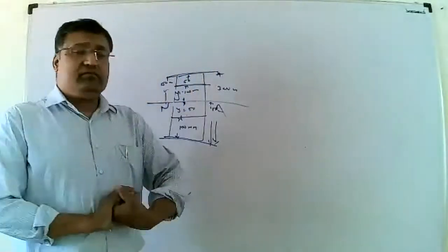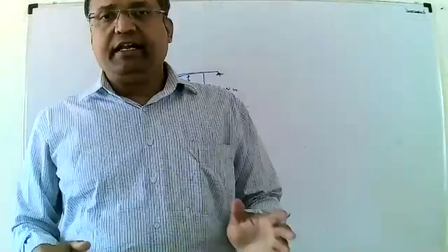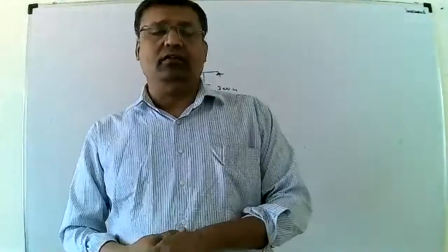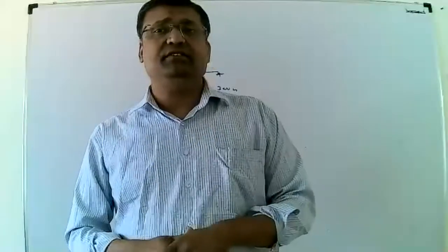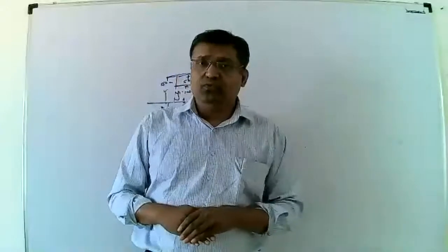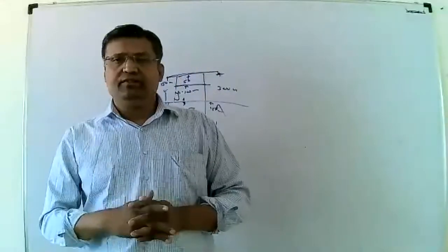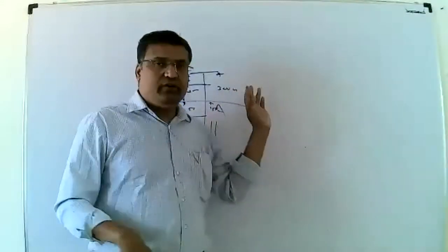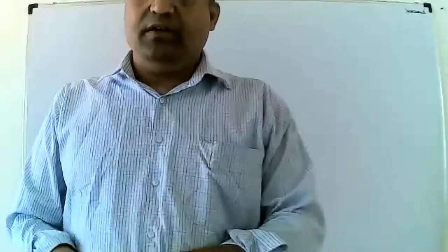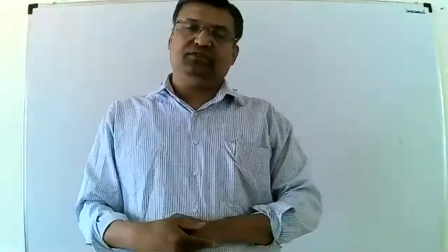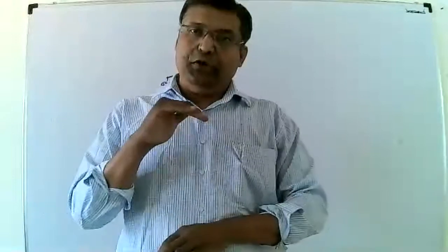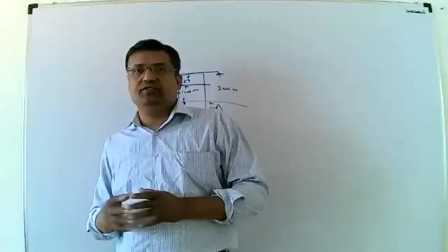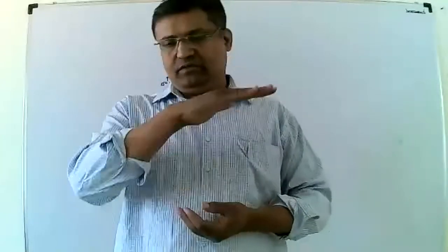Here, the section is always rectangular, most of the time. If the section is in rectangular form, you know how to draw the stress distribution diagram. As you saw in the previous problem, the maximum shear stress is generated at the neutral axis, whereas at the top and bottom extreme layers the shear stress is 0.